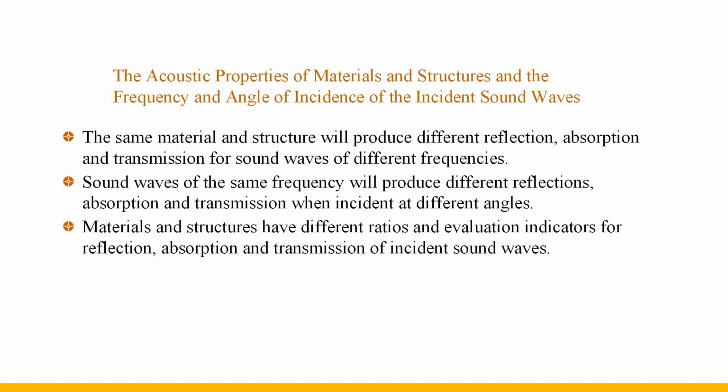Any kind of material and structure will reflect, absorb, and transmit incident sound waves. The proportions of the three are different. The proportions vary with frequency and incident angle, and the evaluation indicators of the three characteristics are also different. Therefore, materials and structures are determined on the one hand according to the characteristics with a relatively large proportion, as sound absorption, sound insulation, or reflection, and on the other hand according to the function that is mainly considered during